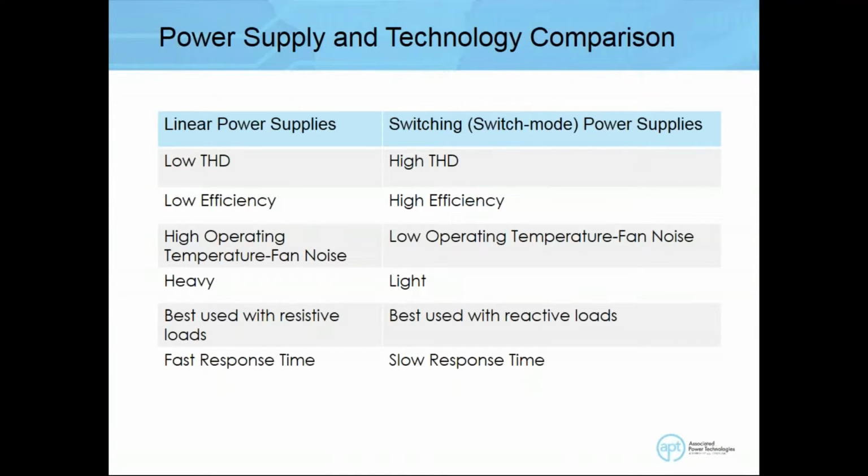It's best used for reactive loads. So if you're trying to power up a reactive load that may have a higher crest factor or a higher inrush current, a switch mode power supply is able to handle these additional requirements because you're adjusting on the fly what the output may be. So majority of times, when you have a motor that needs to come on or an inductive load that has a requirement for high inrush current, a switch mode power supply is able to handle this properly.